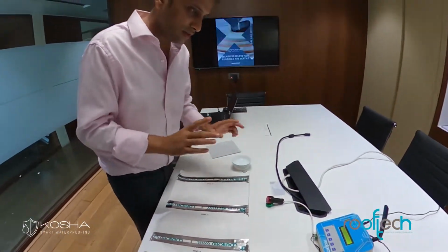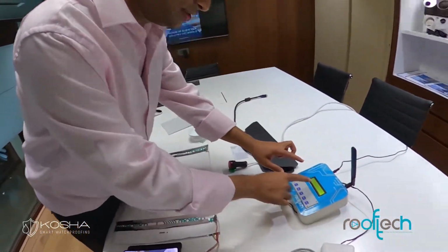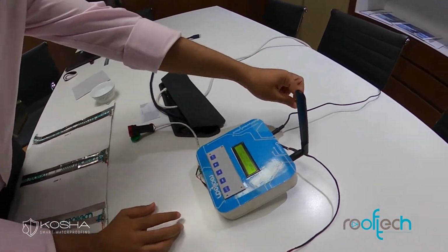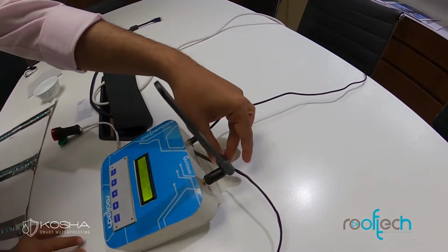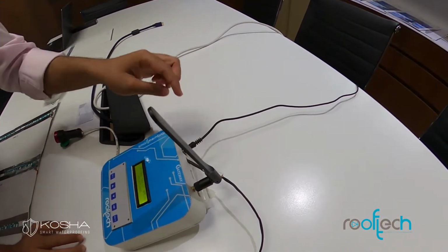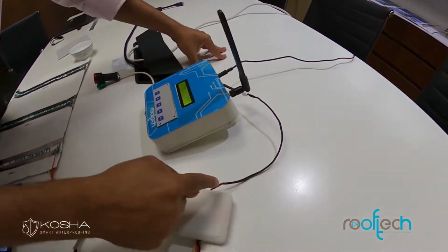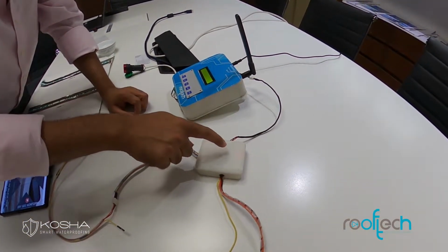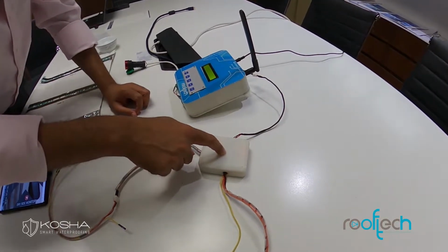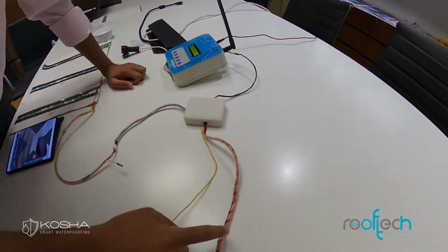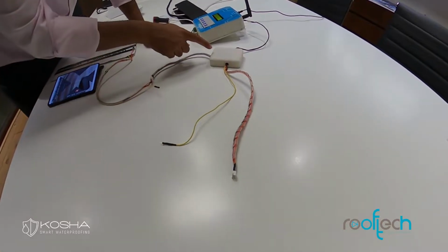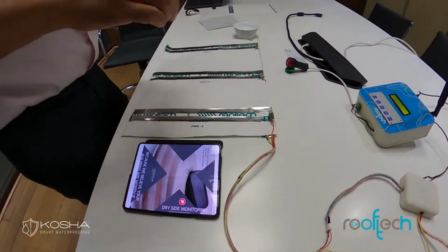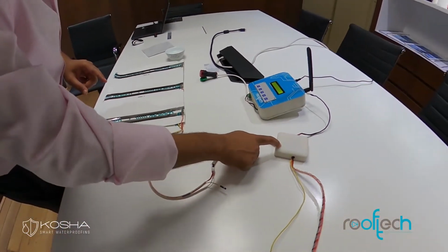Now, starting with again the three component system, first being a communication gateway. Simple system. It has a power in. From this terminal, it connects to the first sensor node. This is the in terminal of a sensor node, this is an out terminal, and from here there are 10 zones which can be plugged to one sensor node.